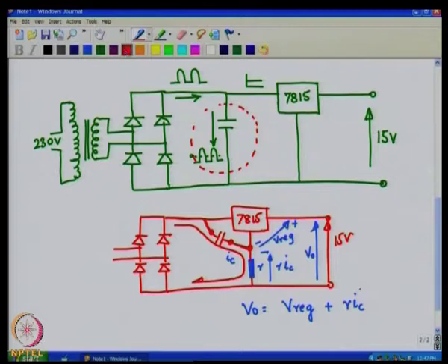Now, this portion is unregulated, is something that we do not want. We do not want it to come to the output, but this is an error that will come on to the output, deregulate the output by virtue of routing which is as such like this, whereby the capacitor current flows through this parasitic component small r here lowercase r, which is trying to couple some of the unregulated portion to the output. This is one of the issues that can occur when you are doing the PCB routing, layout and routing, and one must be careful about this.